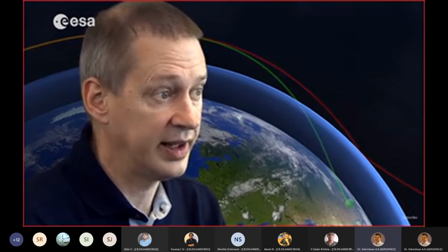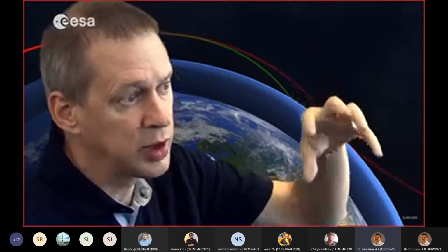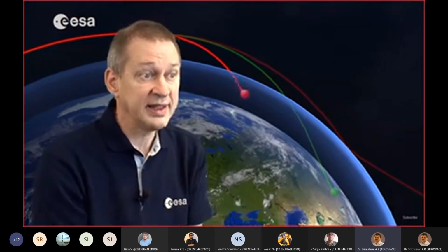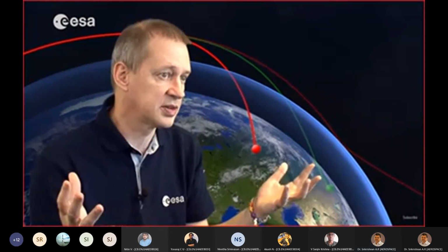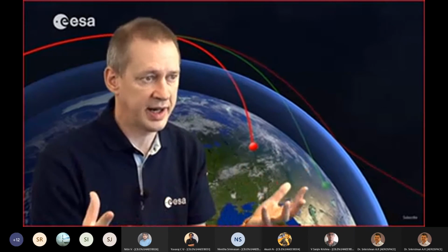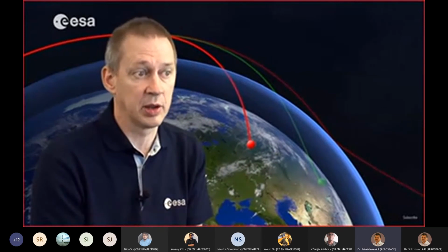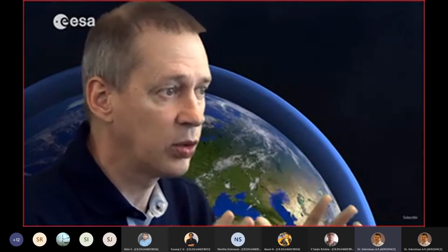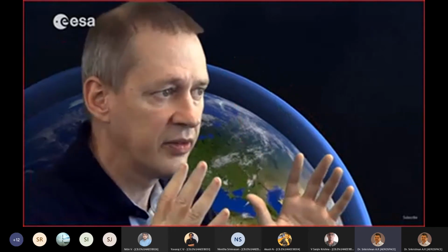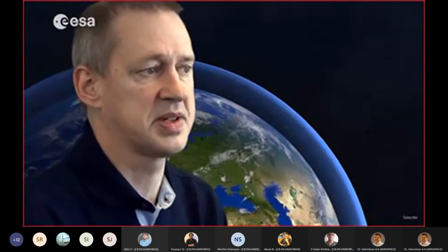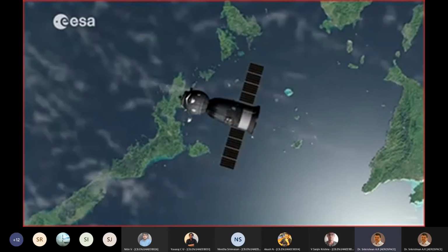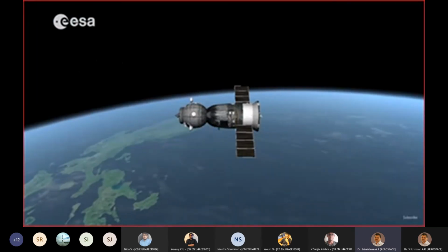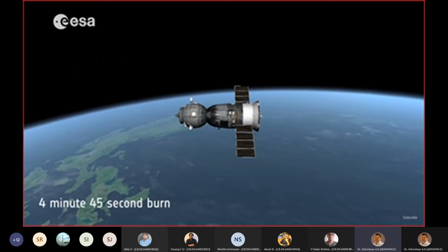At the same time, if it were too shallow, it would probably burn because of the high temperature that would result. So that's why that green line, which is what we refer to as a narrow corridor for approach for re-entry, is important. And in each of those instances, they come across what we are going to see as the specific physics related to hypersonic flow.